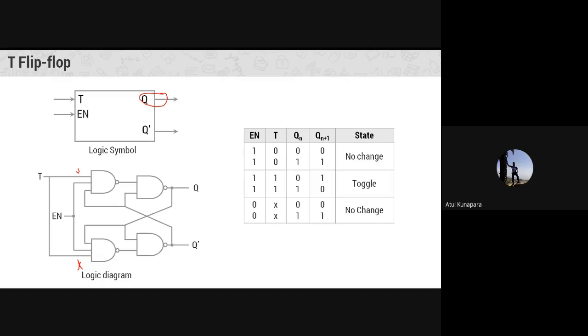So according to that, now suppose you want to store data. Let us say I have 4-bit binary data, suppose 0101. If you want to store the 4-bit data, you require 4 flip-flops, right? And you can connect them in that manner, and you can set the value of 2 flip-flops to be equal to 0 and 2 flip-flops to be equal to 1. So in that way, you can get your data 0101 stored in those flip-flops.